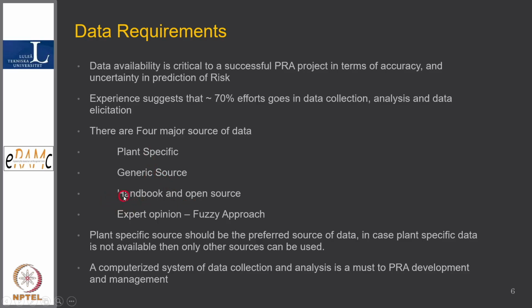Then handbook, this is more true for electronic components, because at component level, at card level, handbooks facilitate a very good mechanism for estimation. Of course, now MIL Handbook 217 Plus has come. Earlier MIL Handbook 217 was there, but then there were doubts regarding whether it is good or adequate. So the physics of failure methods have come. So a lot of advancement has taken place. So either you can call POF at lab scale or at an advanced plant level, or we can use the handbook approach.